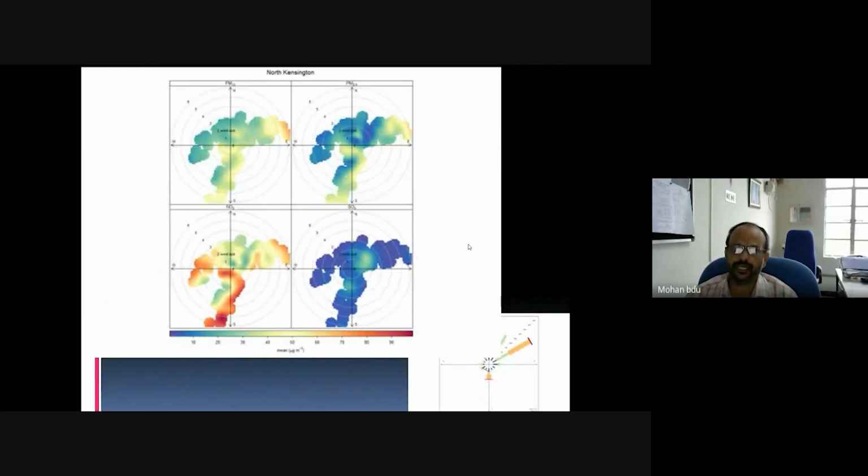So the Openair package also can give you the pollution dispersion, maybe in which direction the pollution moves out and what will be the concentration. It's very clear, and this can also be overlaid or coupled with the GIS data, and we can figure out which particular location will have, for example, here whichever is shown as red has a very high particulate matter, that is more than 90 microgram per meter cube of PM 2.5.